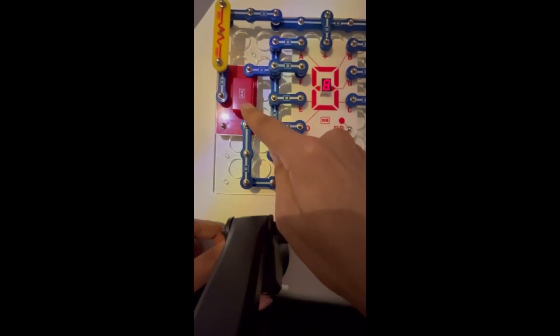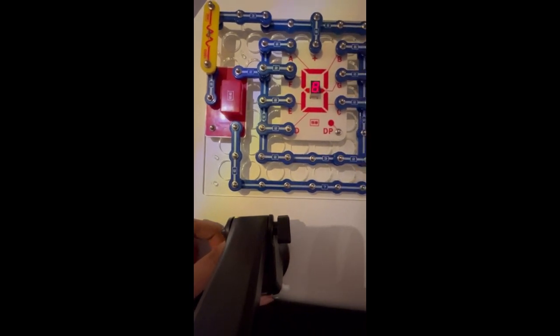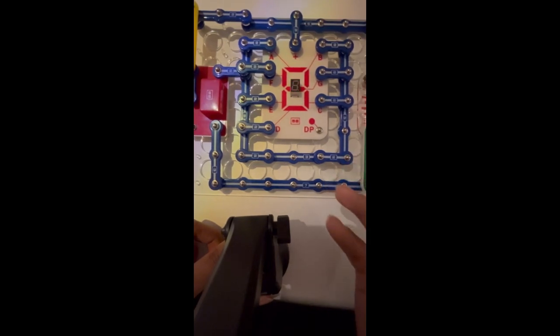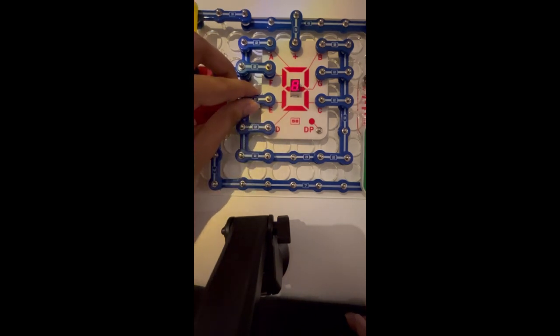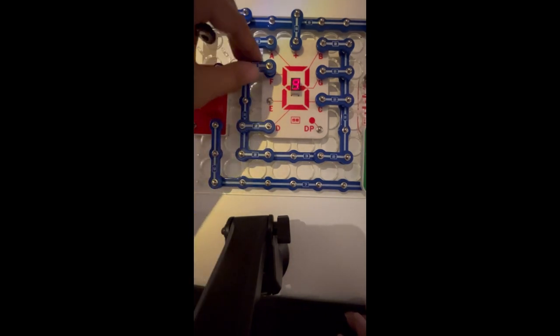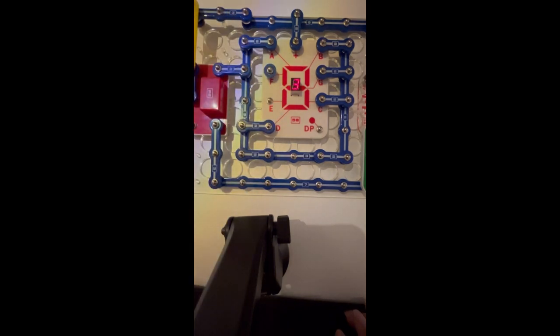This part is close to the counter, but it has fewer functionalities. For example, it has the pulsing, but it does not do the incrementation. Now, if we take out this part, this E part, from the 7-segment display, we can make the representation of 9. If we take out this part, which is F, we can make the representation of 3. And this is what the hardware is about. It helps in visualizing what the project was doing.